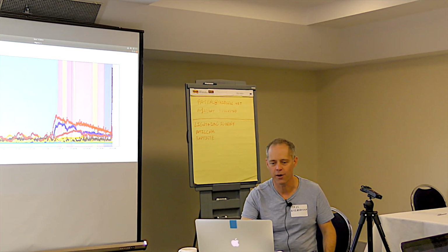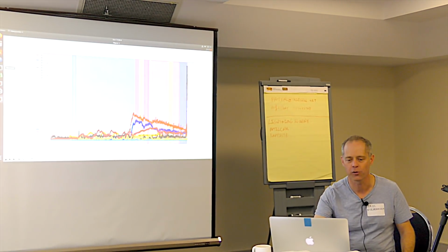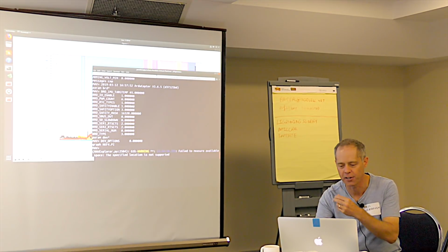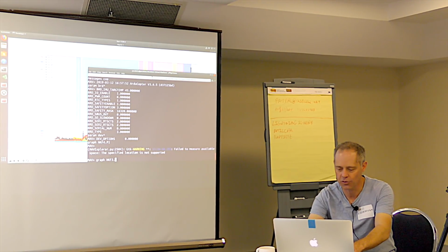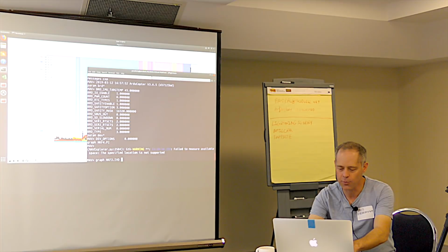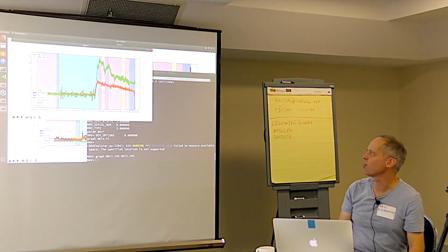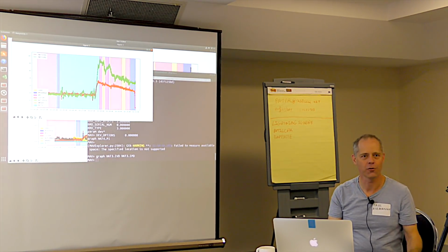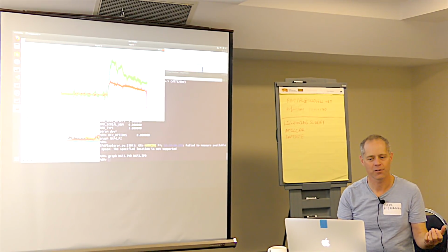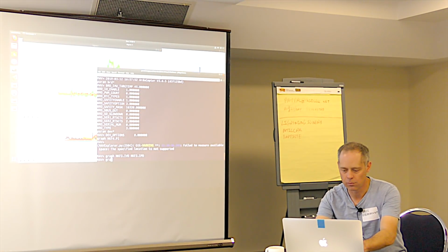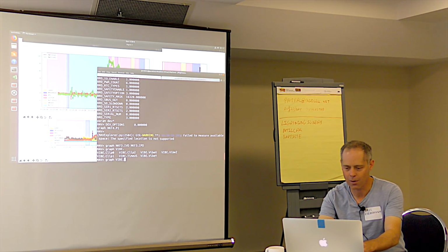So, okay, what are the other clues there? Well, let's have a look at the innovations for both, not just the magnitude, the normalised innovations. Let's have a look at the actual innovations in engineering units of metres and metres per second. So we graph NKF3.IVD, and then we do NKF3.IPD. We pull those up, and yeah, they're both positive. Now, when I saw that, my first reaction was, that's vibration, and it's just affecting one IMU. But then I had to look at the vibe levels. Graph VIBE, I'll look at Z.